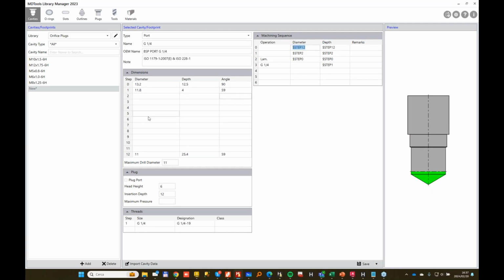There you can put all the information you want, and the insertion tab is this one. So that's one geometry, and normally this drill is much smaller. Let's say it's like this. So we have the 1x4 BSP thread, we have the step 1, which is the tap drill, and then we have the pilot drill that goes into the cavity.